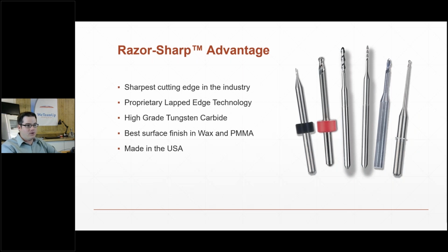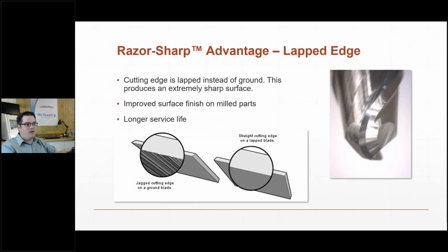They're better than other uncoated tools because they have our geometry that's developed for dental, and they also have a surface treatment feature to the cutting edge that makes it much sharper. And so since the tool starts off sharper, it wears longer. So in zirconia, you'll get 150 units instead of 50, comparatively to another carbide. And then in soft materials like wax and PMMA, much better surface finishes and fits.